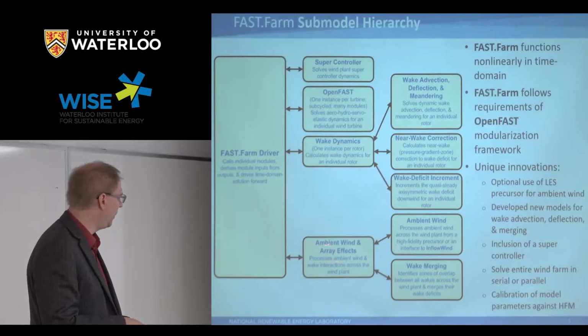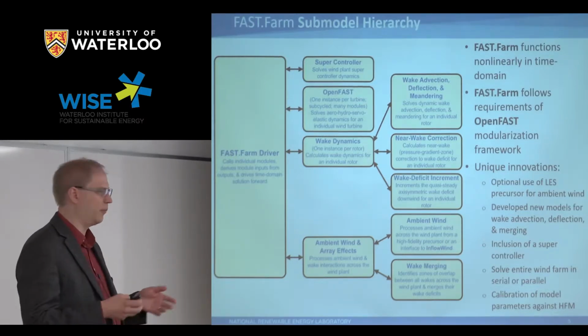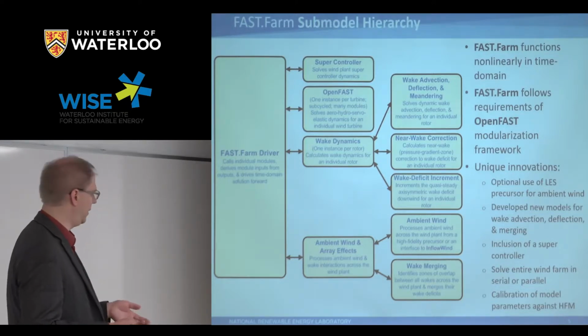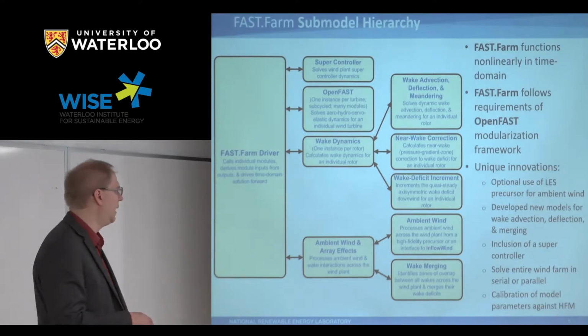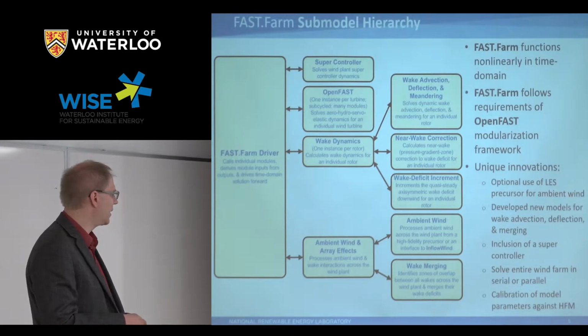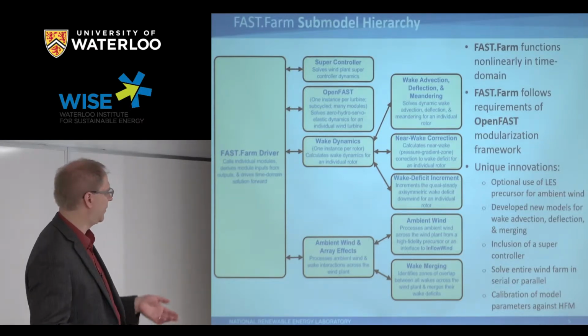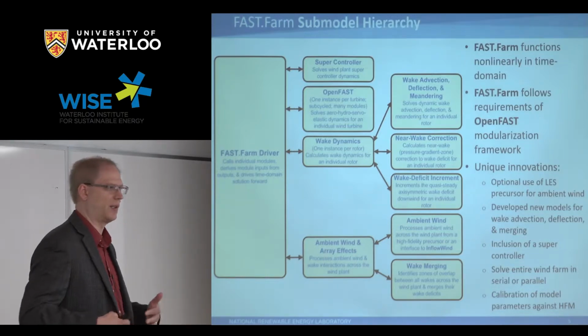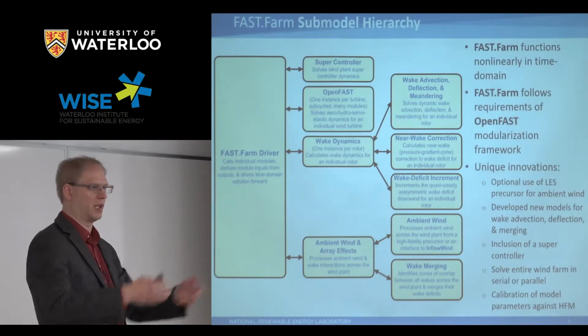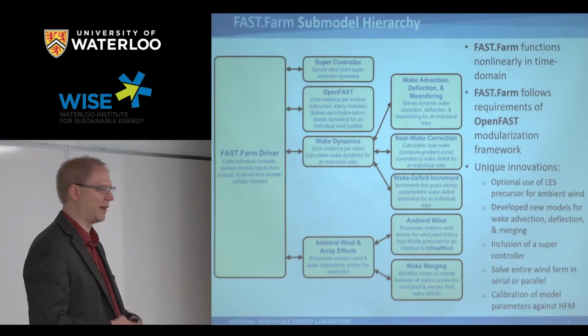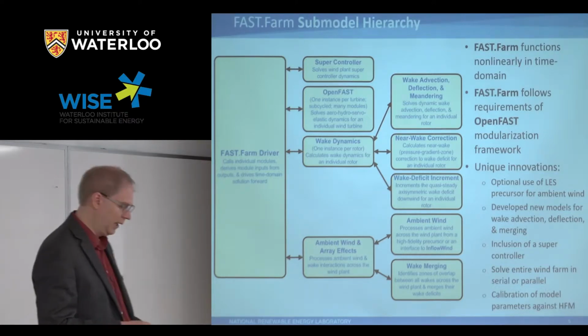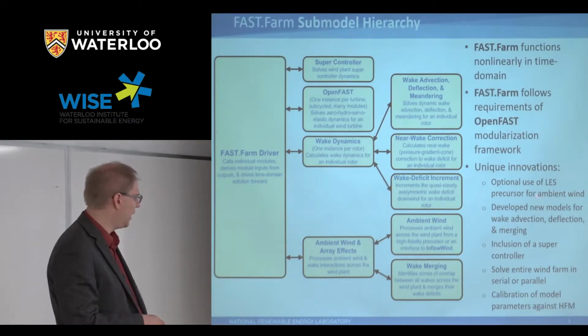First of all, when we do ambient flow over the entire wind farm, in addition to having a very simplistic, what we call synthetic wind generation, we also allow the user to specify a full large-eddy simulation precursor domain. Without modeling turbines, those simulations take on the order of a day to run. So just fairly coarse grids flow over the domain to get the right turbulent structures for whatever atmospheric condition you're simulating. So you can run those again in about a day.